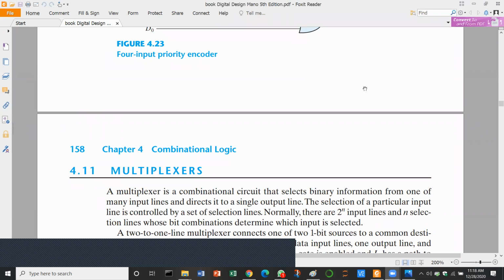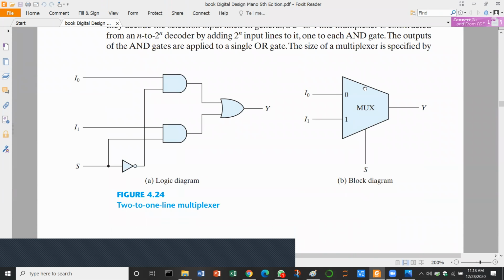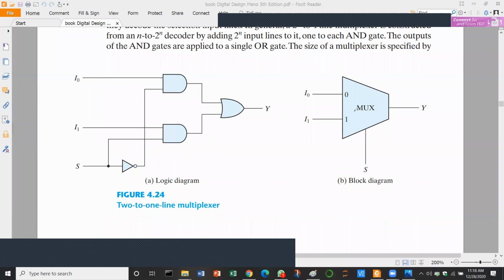So I just need to go to, okay, so this is an example of a mux, a multiplexer, and remember it's a 2 to 1, because it has 2 inputs and 1 output. So a 2 to 1 mux only needs 1 select line. The internal diagram is also shown here, how it primarily works, but the concept is very simple.